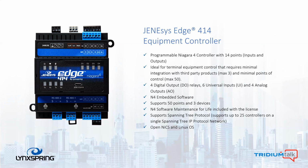And its intended applications are those terminal unit controllers, the larger volume assets within a building. You can see that it can integrate up to three devices, limited to 50 points. Its applicability, of course, is its small framework and its communication. It can communicate via serial, or it can communicate via IP. Something that's added here, and this is true for 514 as well, is that it's capable of communicating over a spanning tree protocol, so on and so forth. So next slide, please.